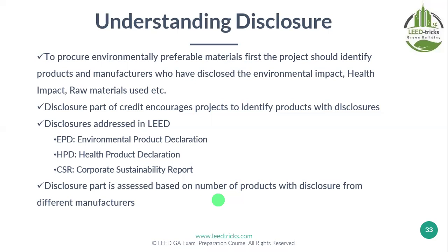So a specification writer should know what EPD is, what material disclosure is, and what the requirements of LEED are, and implement them in the project documentation, because it might stay in the LEED reference guide forever. Even after the project is finished, they cannot do these credits. So specification writers now need to know very well about the material requirements and include them within the product specification or project specification and the other documents in the design.